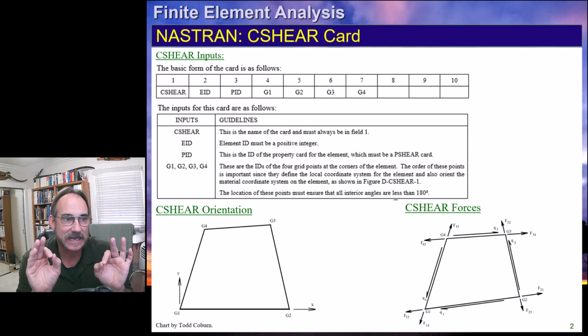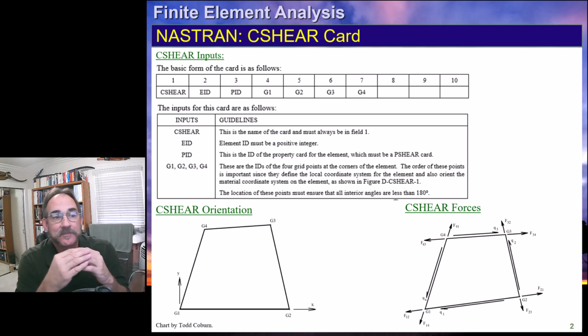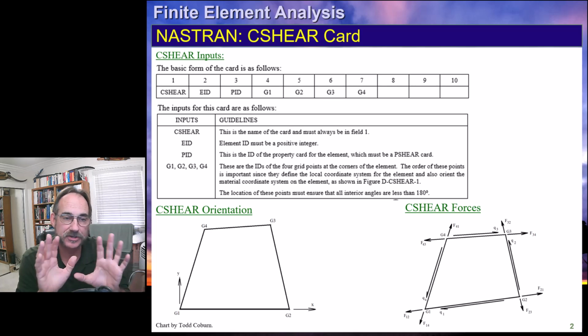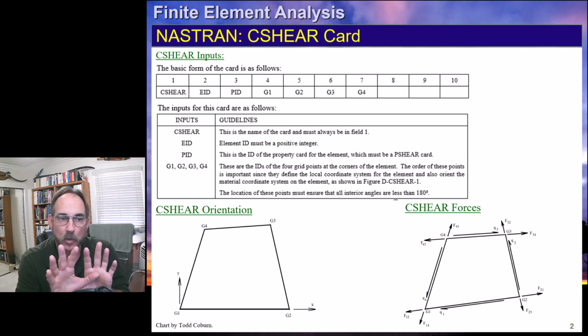However, to temper that statement a little bit, in the process of modeling our shear behavior, they also develop kick forces. So there's two things. Part of it is intuitive, the other part is not intuitive. We're going to have a shear flow in the panel. That's the shear that is carried, written as a shear flow, pounds per inch.